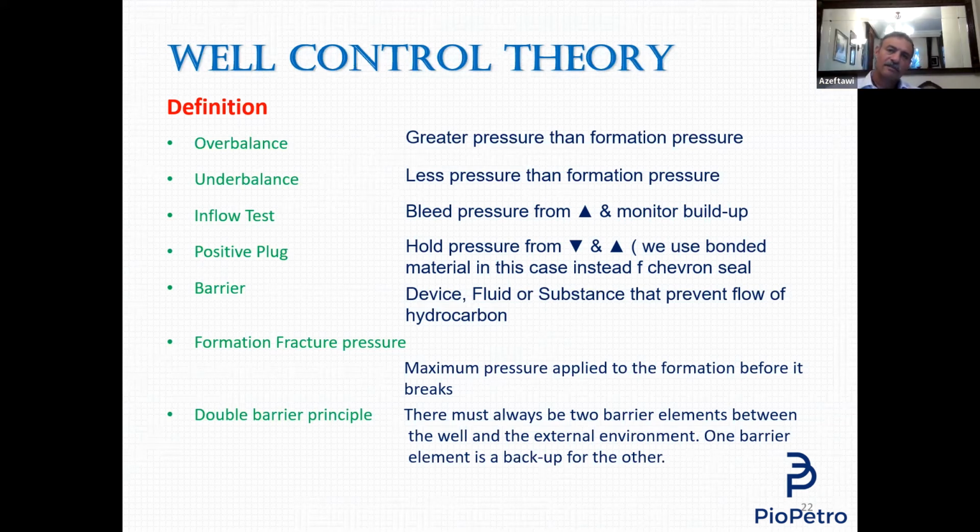Before I do that, I cannot do that against one valve closed. I have to close another valve in the Christmas tree, which is the master valve, the upper master valve. So I am testing, I am opening now against two valves, not one. But these two valves are inside one barrier, which is the Christmas tree.